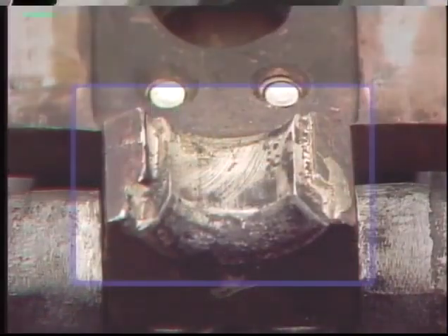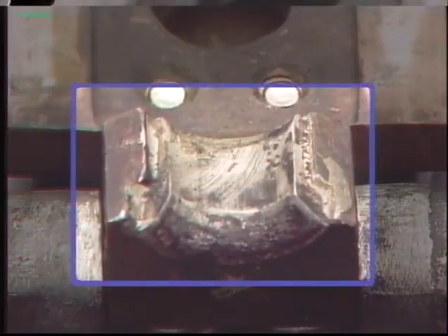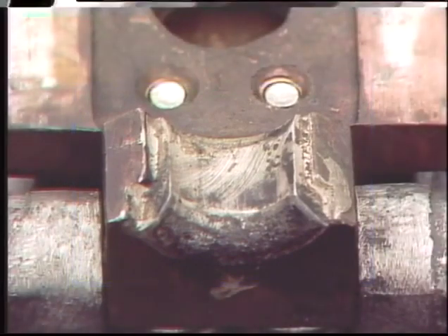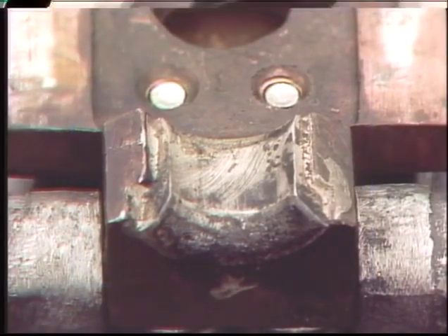In general, some discoloration and pitting is not harmful, as shown here. However, if an arcing contact is severely pitted or burned, it may need to be replaced. Any problems that are found during an inspection should be corrected. Replace parts if necessary, repair damage, and tighten loose connections. Anything that could affect the proper operation of the breaker or that could cause it to fail should be taken care of while the breaker is out of service.